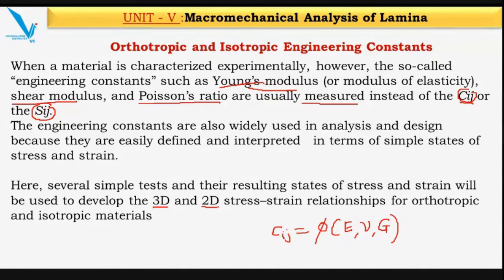If it is a flat composite plate, where the two dimensions are sufficiently larger than the third dimension, which is thickness, we will not analyze this as a 3D, but we'll analyze this as a 2D. If I take this lamina with a small thickness, suppose 5 mm, we will generally analyze it as a 2D structure.